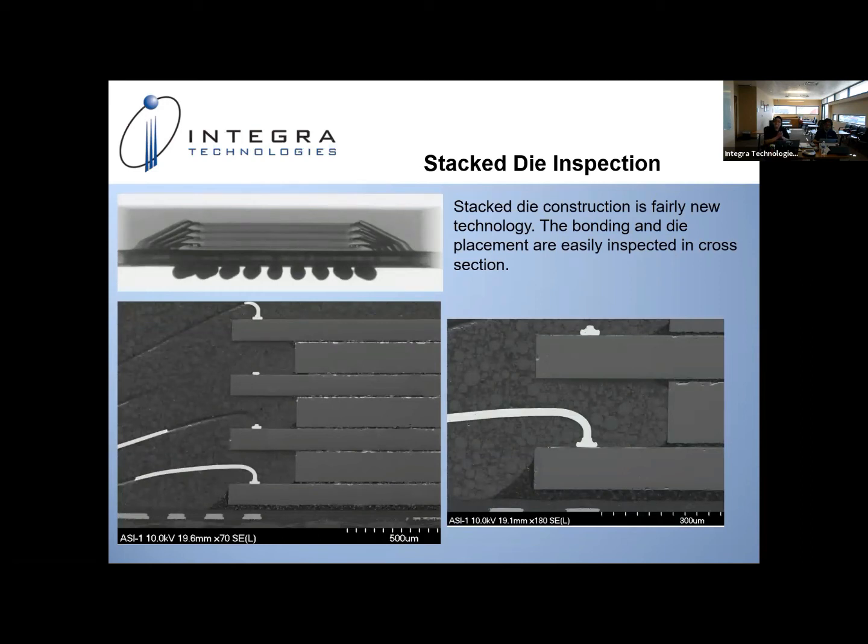And I got a couple more for you. All right, so stacked die construction. Stacked die is fairly new in the industry. It's not really well covered in the MIL standards just yet, but it's super cool. It's sometimes called 3D technology. The top left-hand image there is an X-ray. You can see the multiple stacked silicon die.